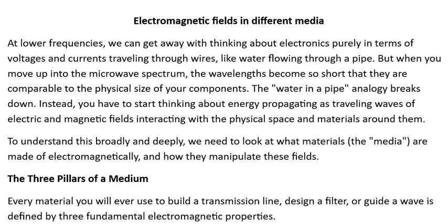But when you move up into the microwave spectrum, the wavelengths become so short that they are comparable to the physical size of your components. The water in a pipe analogy breaks down. Instead, you have to start thinking about energy propagating as traveling waves of electric and magnetic fields interacting with the physical space and materials around them. To understand this broadly and deeply, we need to look at what materials, the media, are made of electromagnetically and how they manipulate these fields.